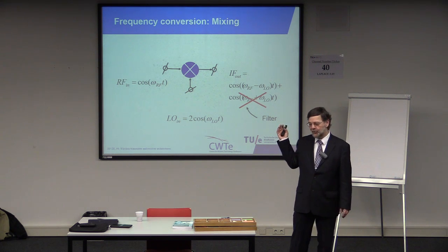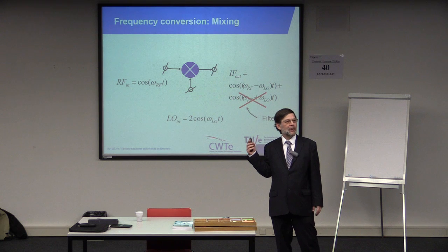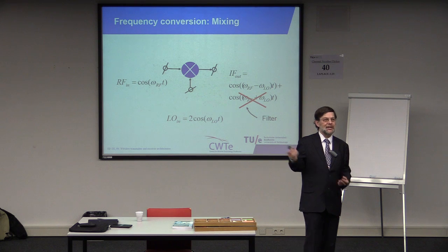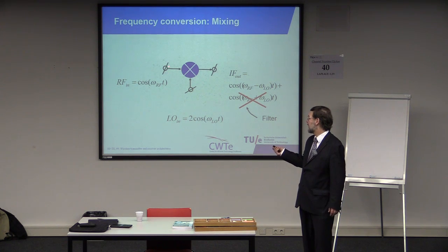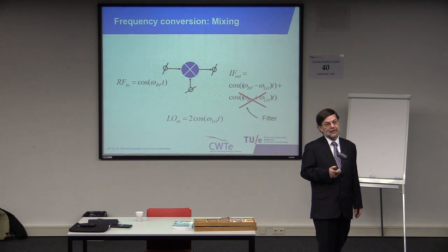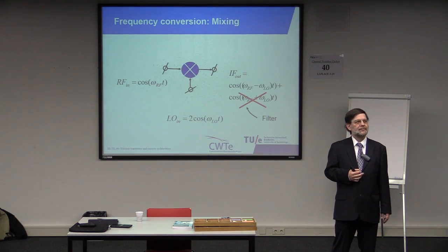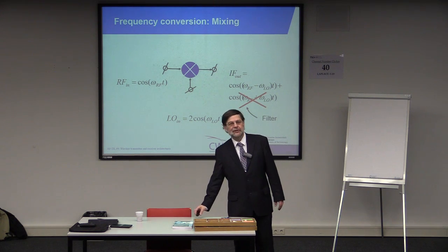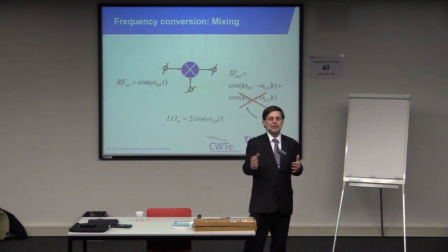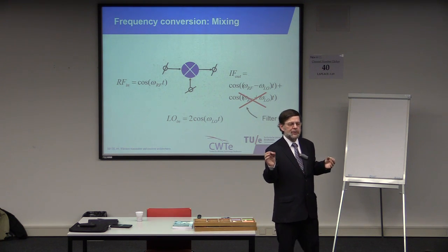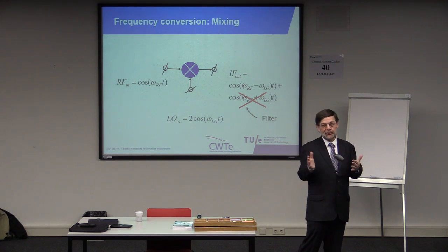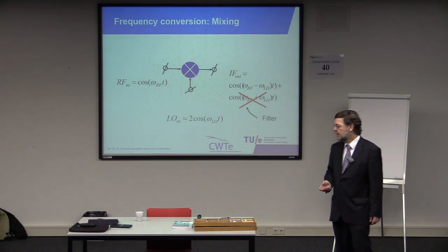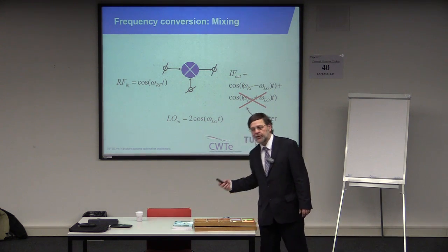If you think about frequency conversion, what kind of operations can we consider? Why do we go to multiplication? Could we do addition, for example? Could I just add this signal to that signal and then expect the output to be shifted in frequency? No. Because any linear operator has the same output spectrum as input spectrum. Output frequency components, I should say, as input frequency components. There's no frequency shift possible. At least if it's linear and time invariant. So obviously we need something that's nonlinear.